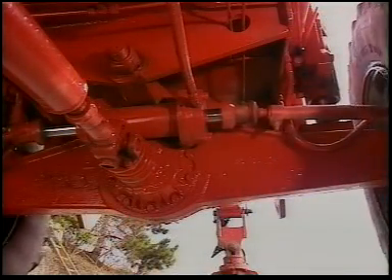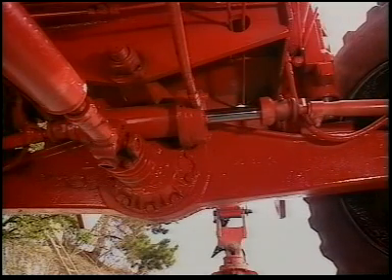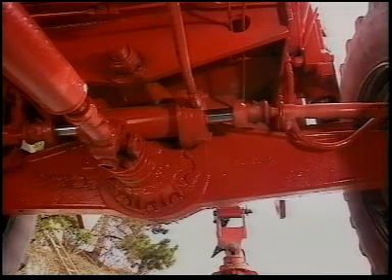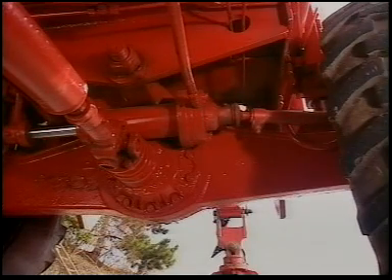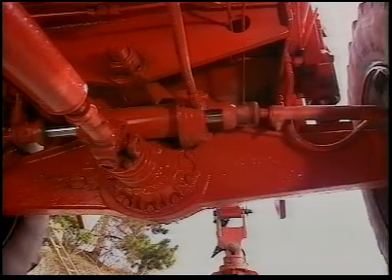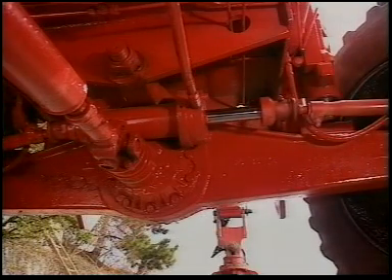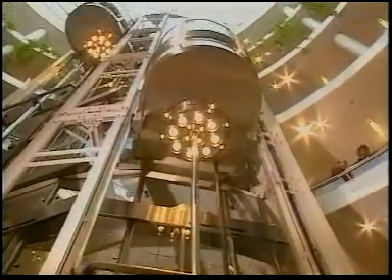Varying piston speeds would be undesirable in this hydraulic steering mechanism because steering movements to the right and left must be at the same speed. For this reason, a balance cylinder was used in this case. A balance cylinder is one with a double-ended piston rod. An additional advantage of a rod like this is that it can move elements on both sides. A hydraulic cylinder with a long stroke and a relatively short length is the telescopic cylinder, which comes both as a single-acting and a double-acting cylinder.